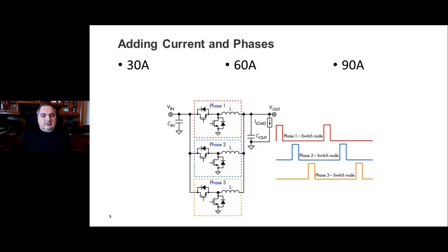So this is known good technology. Lots of power management vendors do this. This is how we add more power to a power supply to provide more continuous or instantaneous power. We add another phase. A vast majority of manufacturers have multi-phase technologies, whether it's a discrete solution or a module or combination thereof. You could have a discrete controller with power stages which are integrated. But the phase is going to be a power stage and an inductor, and every time we need more current, we need to add a phase.